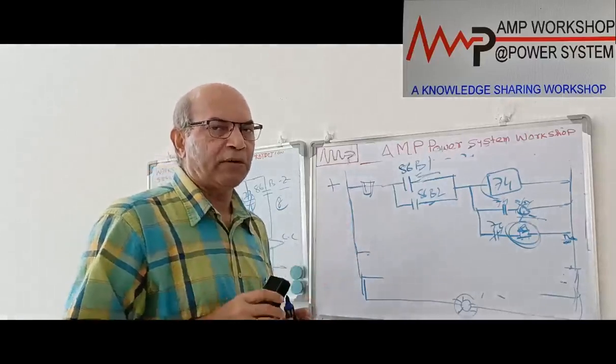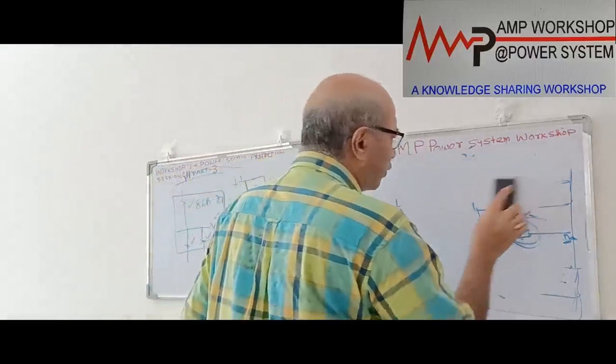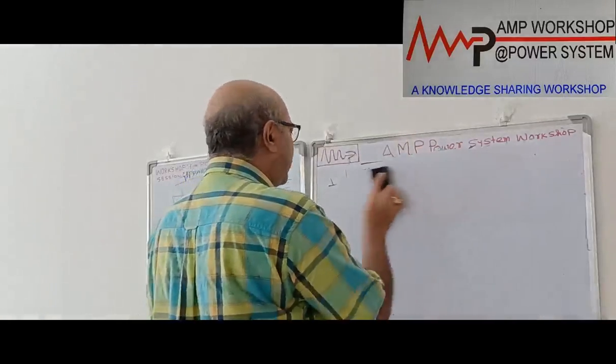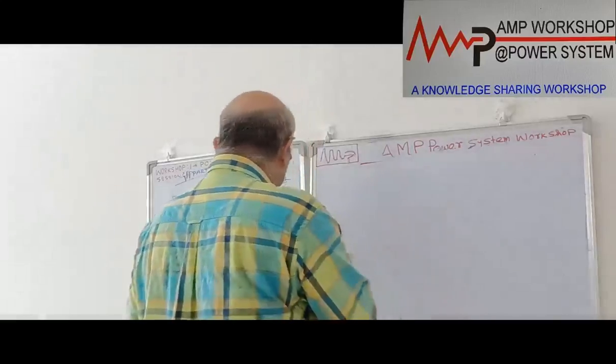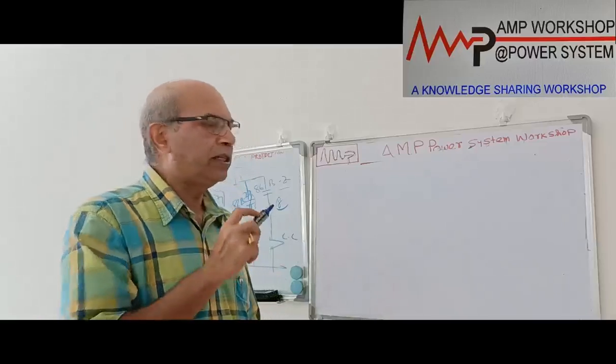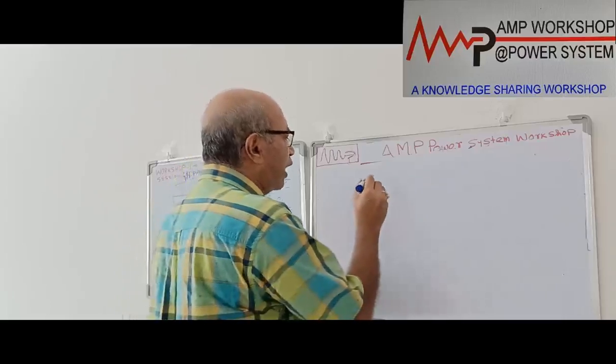What are the basic features required in the busbar differential protection? And the last point we will discuss now is the CT requirement. As we said, the busbar protection CT is very important. Location we have already said. Now some of the basic features of the CT are required. This applies to all the CTs in the busbar protection. Though the feeder rating may be different, all the CTs shall be of the same ratio.